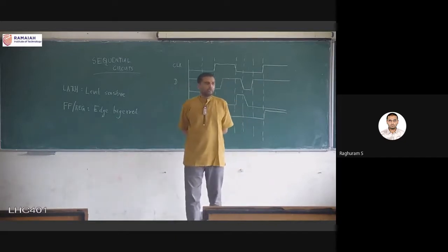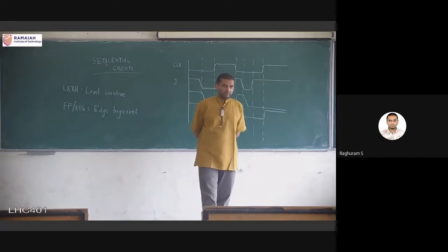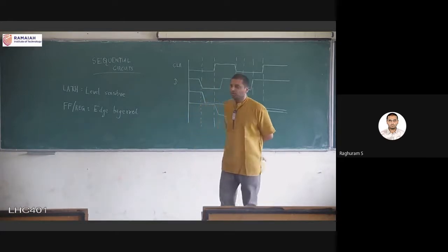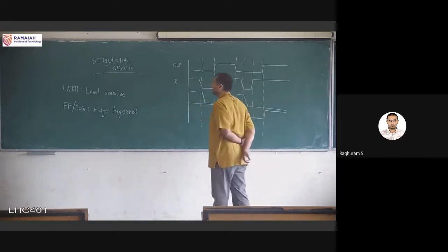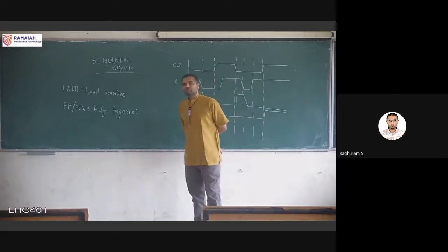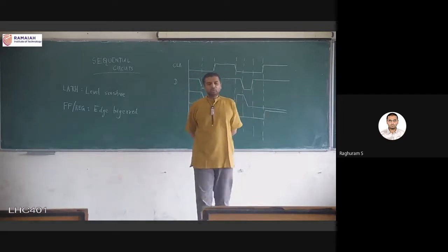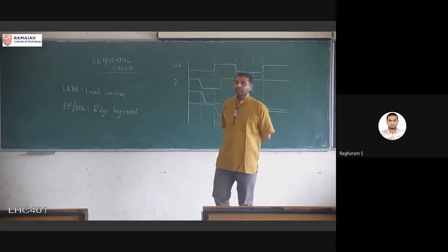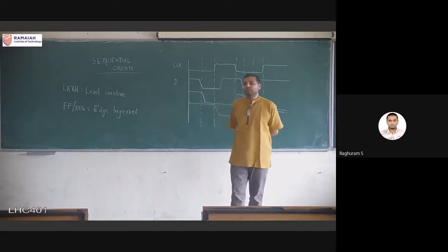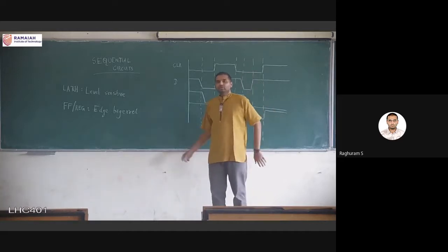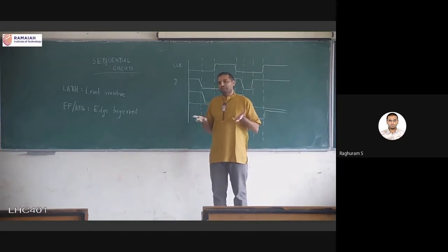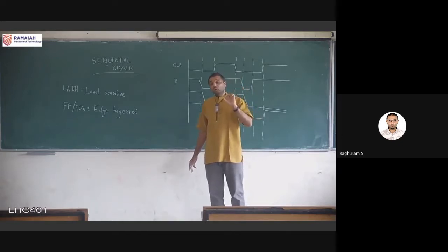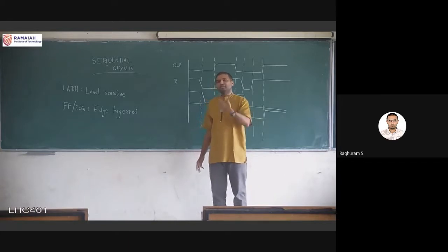Latch and flip flop both are memory elements, both have a clock signal, but the only difference is the latch is sensitive to the level of the clock signal, which means that as long as a particular level is maintained, either high or low depending on the design, the output of the latch will be continuously changing.